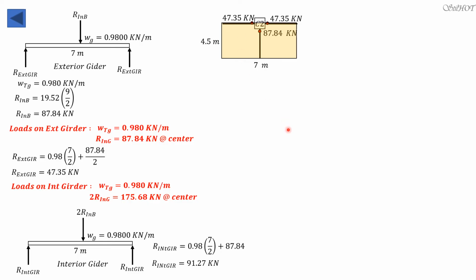How about for the other column? So that's the tributary area, with dimensions 4.5, half of 9, and 7, because this is S over 2. And this is S, and that is also S, so 7 for that column. So this is for the column A3.